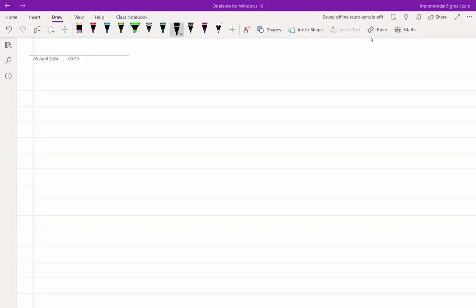Again, the gain is also dependent on gm, which essentially means if the temperature changes, gm changes, and then the gain also changes. So we don't have a very stable amplifier which can give you a desired gain, but the gain should remain constant regardless of whatever happens in the world, right? That type of amplifier we don't have. So that led us to think in a slightly different way. We thought that if we use negative feedback to make an amplifier, then this problem might be resolved.